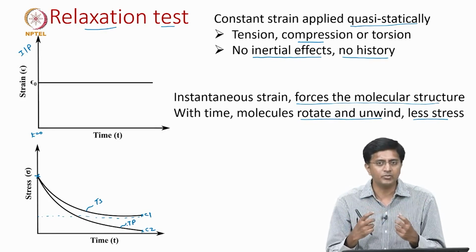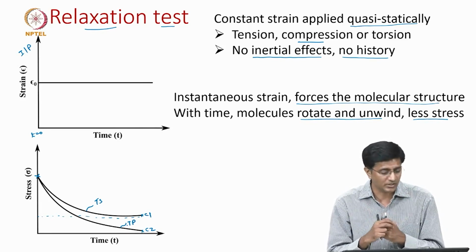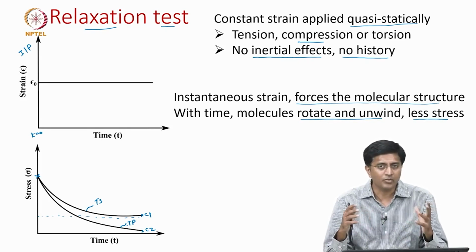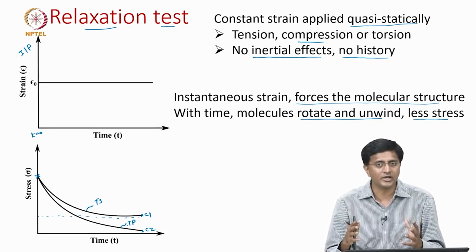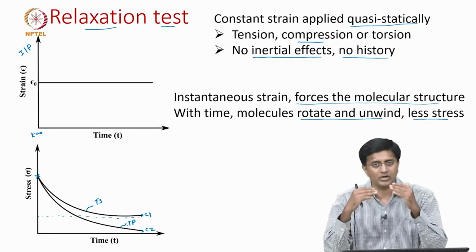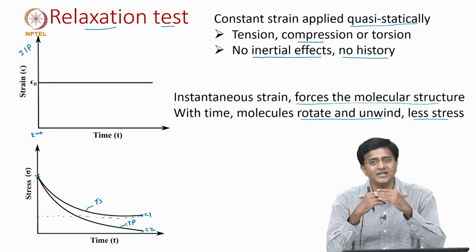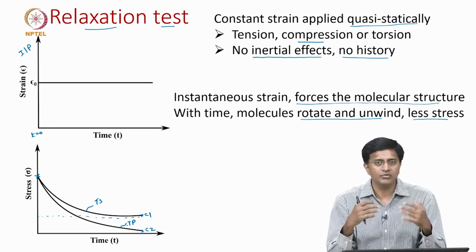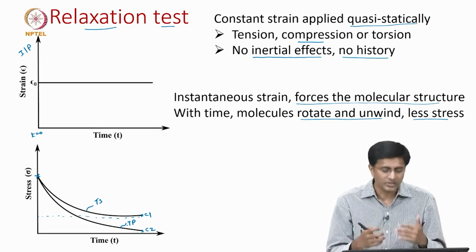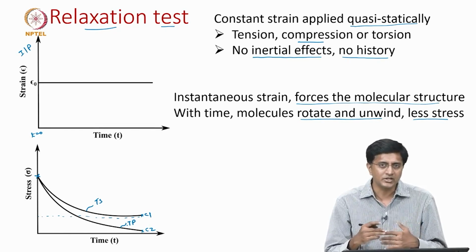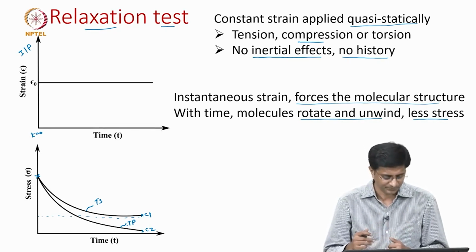Initially it might be counterintuitive to think how a solid polymer like a thermoplastic flows, but we are talking about very long times, when these polymer chains can slide against each other upon stresses, and because of this we get this flow, meaning it comes to a 0 stress state at long times. Okay.